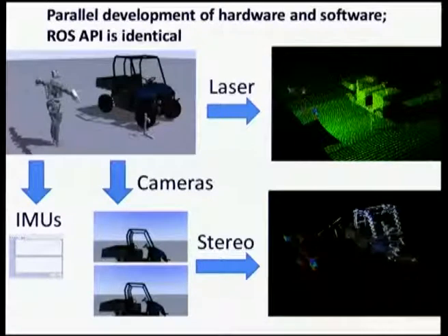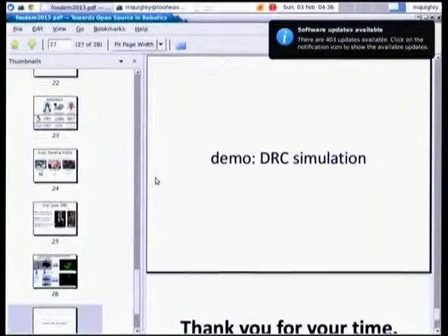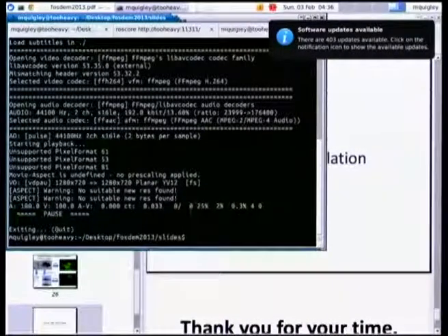And that's actually a geometrically correct projection, so that everything downstream in ROS can run as if it was a regular camera. And we're doing stereo reconstruction there to generate that 3D point cloud of the vehicle on the lower right. We can also simulate things like the inertial units, the force torque sensors, and the robot's wrists and feet, and so on.